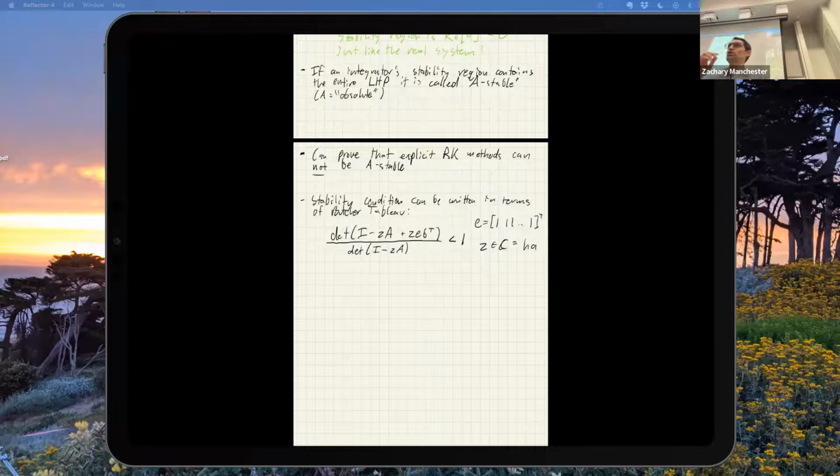Also a really good thing to do is check known solutions. Check for qualitative behaviors that should be there, where you know what the answer should look like. Do a bunch of that, and eventually you'll develop some trust in the simulation, and then you can maybe look at some of this other stuff. And I got off on a tangent.